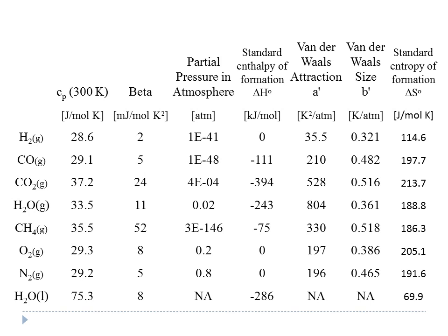Those two columns you need, of course, to calculate the entropy or the enthalpy of a gas or of a liquid, because you need a starting point to be able to calculate from. So we're going to be using these as our starting points. And then I've also given you the A prime and B primes for these gases so that you can calculate first order corrections. So what we'll find here is, with the information we have, we can model almost all gases of interest at power plants except for water.